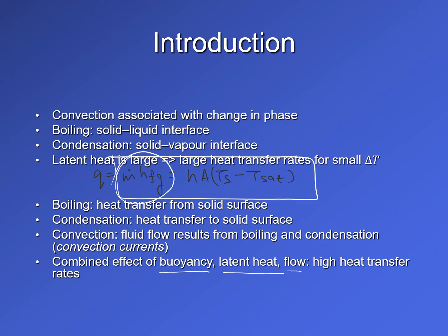We also see that rather than just the flow resulting from the bubble moving, even when the bubbles have still not formed, the fluid above the solid surface is also getting heated, and we are also getting some natural convection currents because of the hot liquid above the solid surface. So the combined effect of all these phenomena results in an increased rate of heat transfer from the surface.